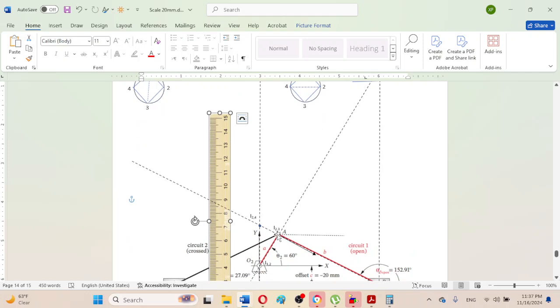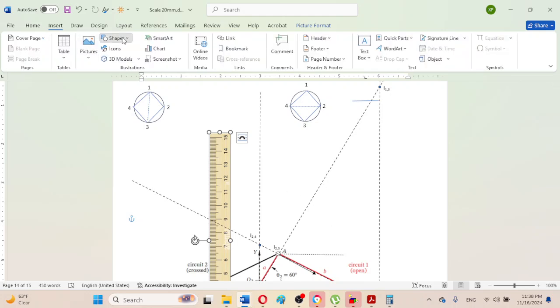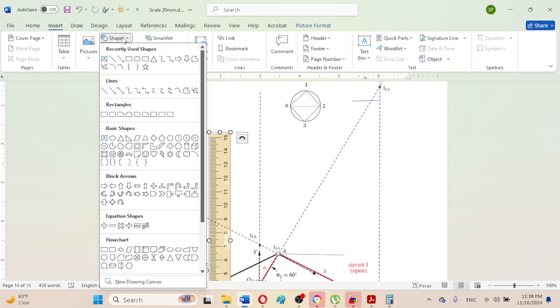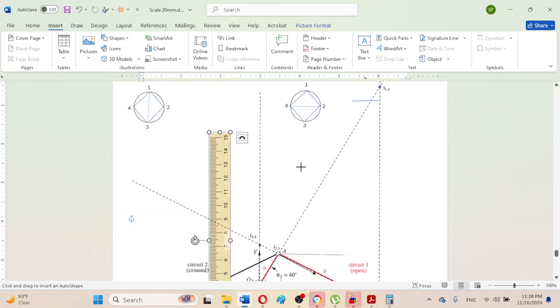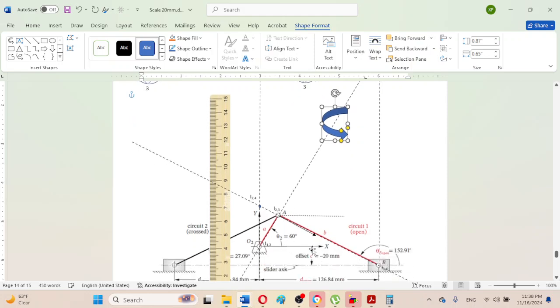This velocity is actually rotating this connecting rod in the anti-clockwise orientation, as we can observe here, or if we can draw some suitable arrow, so I can show it here, that the rotation will be like this. In this way, because this velocity will be rotating this radius, this will be the radius of rotation for the connecting rod.